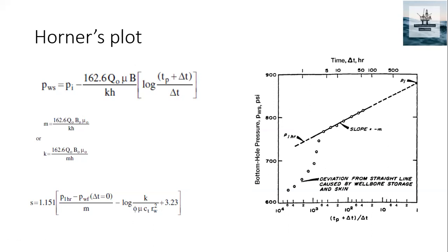So that is PW. Once the production has completely ceased, the wellbore pressure will be at its minimum level. Then once the well is shut in, pressure starts to build from that minimum level to reservoir pressure, equivalent to formation pressure. So that is the value or range of PW. When it comes to PI, that is the initial or undersaturated reservoir pressure. So this is a constant parameter. Wherever we use this parameter, it will have a similar value. There won't be any change in PI.